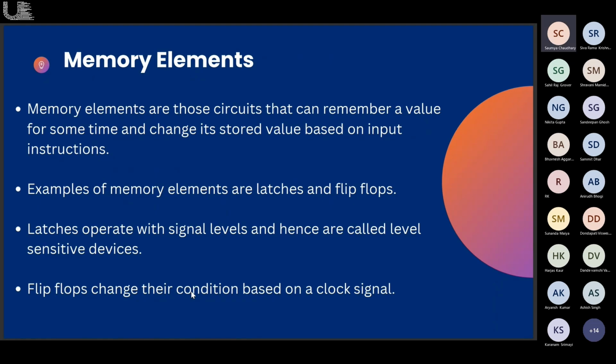As we have discussed the memory element, we feed the outputs to the memory elements. So what is the memory element? Memory elements are those circuits that can remember a value for some time and change their stored value based on the input. So the memory elements are elements which can store the previous outputs and can change them based on the inputs we provide. Latches and flip-flops are the memory elements we use.